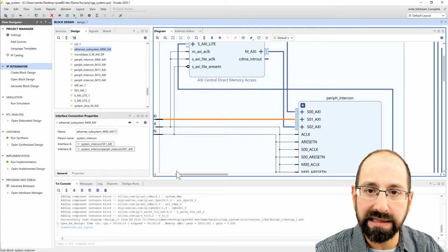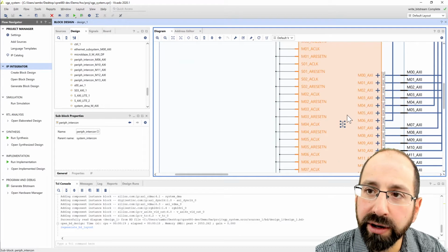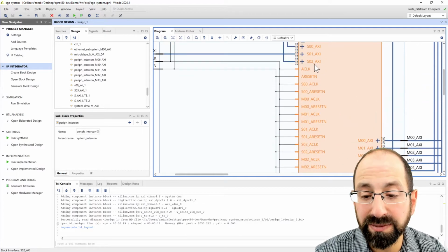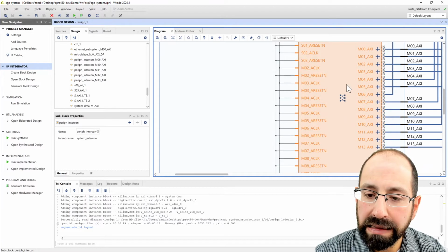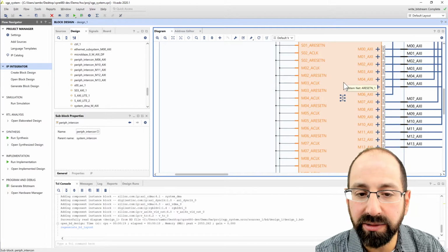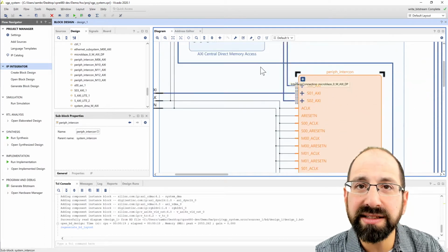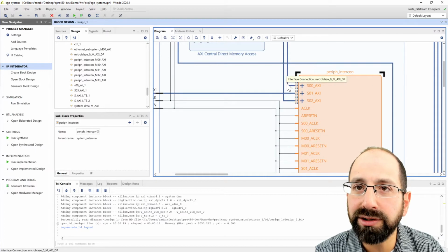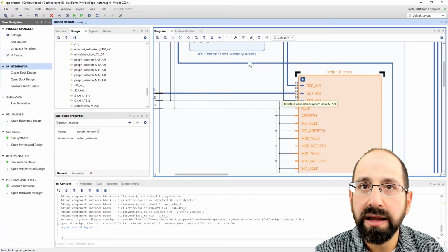So in this case, because of that, the layout looks quite a bit different than our memory interconnect. We have just a few of those bus masters and a whole bunch of those bus slaves, because we have just a lot of different IP cores that we're wanting to connect to the system. So arbitration also potentially becomes important there, but at least for our purposes, outside of some of the memory copies we may want to do, our Ethernet gets access and gets the priority for that particular system.